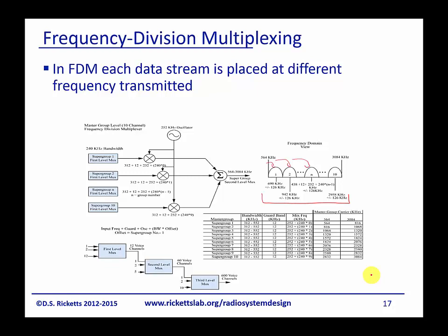The one thing that it's just starting to happen, but it's not really mainstream, is that in the past, fiber optic has been a binary on-off key. So you get a 1, a 0, 1, a 0, 1, a 0. And the reason they did that is they can basically translate, like I said, 40 gigabits or 100 gigabits over optical fiber because the transmission loss is so low. It's very difficult to build the electronics that can do 40 and 100 gigabits, but the basic idea of the fiber is it's open to almost unlimited bandwidth, or I'll say relatively unlimited bandwidth.